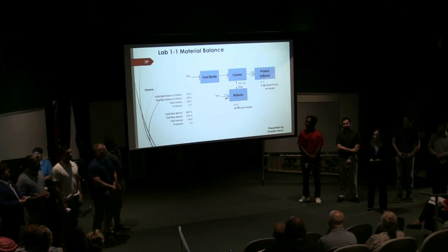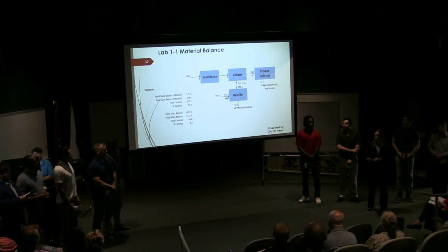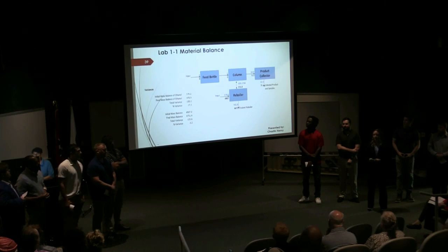Our ethanol balance didn't close within 10%, and we attribute this to error in hydrometer reading or determining concentration. Another source of error is product still left in the distillate tank because it has a flat bottom. We did close our overall mass balance within 3%, and our primary source of error here is heel left in the receiver, reboiler, and the column.